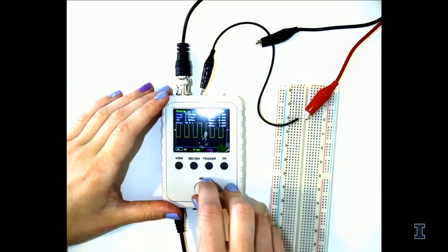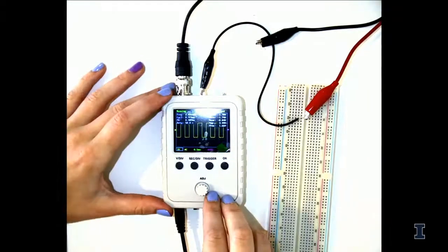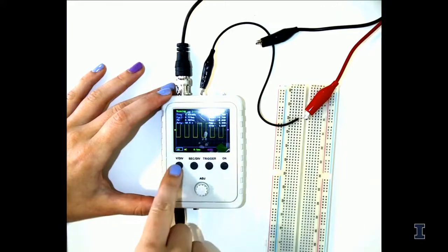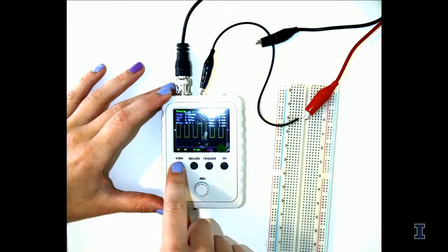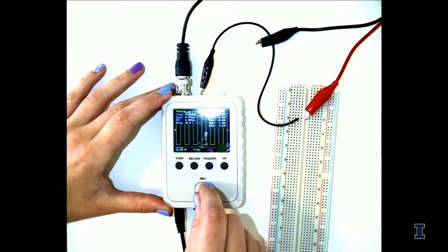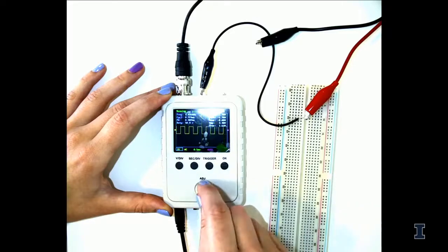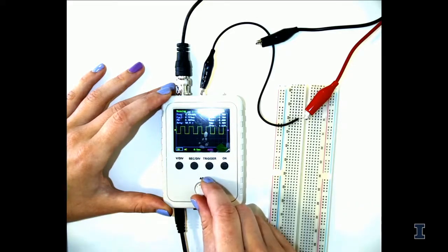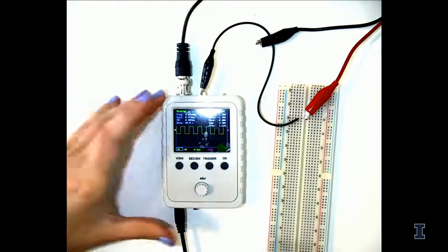All right, so if your signal, let's say it wouldn't fit on this screen, this one has a pretty nice signal for example purposes. But how you can adjust the oscilloscope is on the left. If you press V/div, this is your voltage increments. If you press it so that it's highlighted, you can then use the knob to adjust what your increments are going to be. Up and down, you can see that the value is changing. Right now we're at 2 volts. You can see it's still the same signal, just on a different scale.